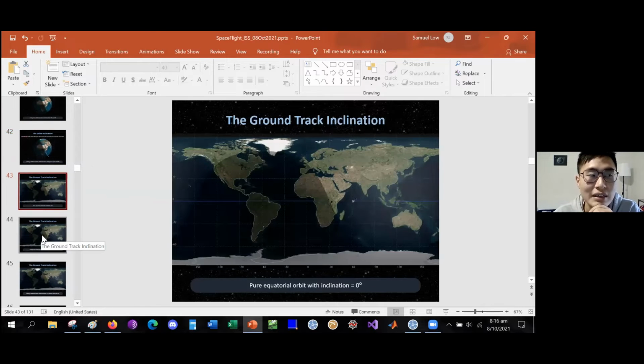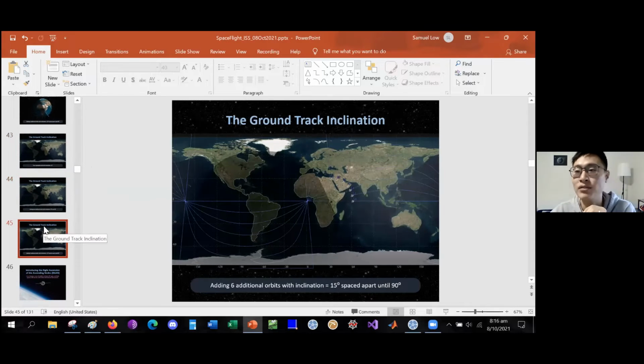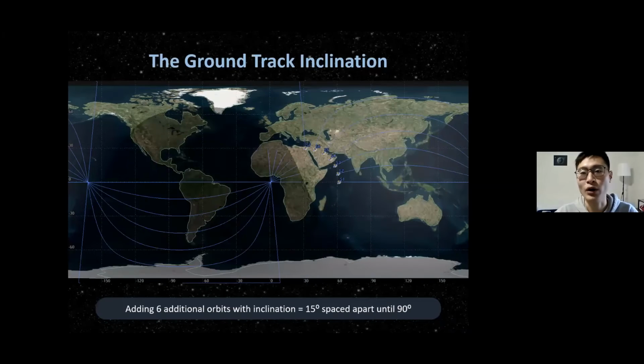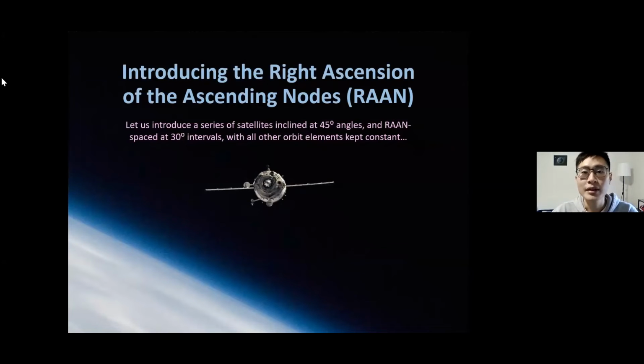Yeah, so yes, it is computable, and usually in the case of an impulsive solution, by impulsive I mean you can immediately apply a sudden change in your velocity vector, there is an optimal solution for the change in velocity, or equivalently the change in energy, that you would need in order to change from one orbit to the other. Okay, two questions. We can calculate the velocity from the difference in potential energy, right? It is easier to do it in a circular orbit because your velocity is constant.